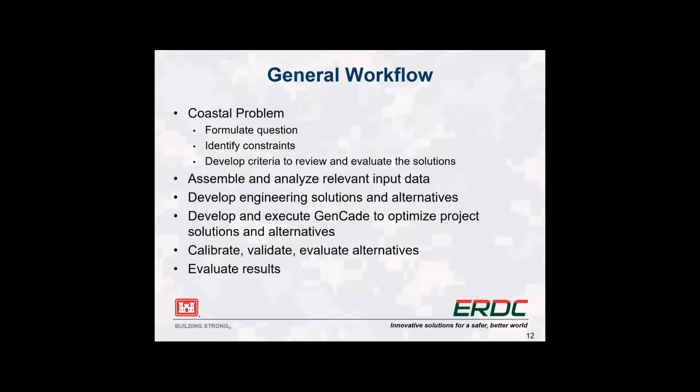Then develop the model, calibrate it to whatever historical data you have, and validate it, or check your calibration. Then evaluate your alternatives and look at the results of the various alternatives you run through. You might be varying the breakwater transmission or the locations of the breakwaters, groins, just whatever engineering solution you're looking at.